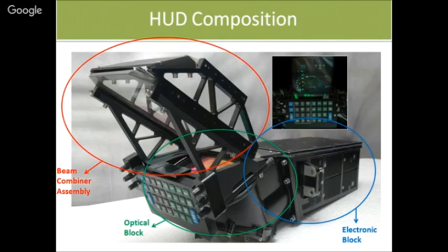Now the speciality of these beam combiners is that thin film coating is done on them. They are so coated that they reflect only one particular wavelength, 545 nanometer yellowish green light, which is coming out from the CRT. It is a monochrome CRT, it displays only yellowish green color, and that yellowish green color is being reflected. All other wavelengths are passed by this.